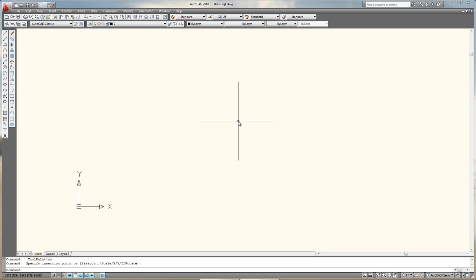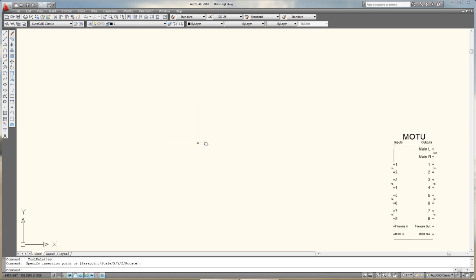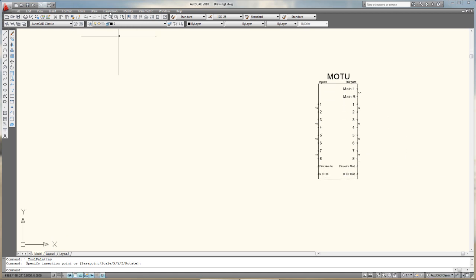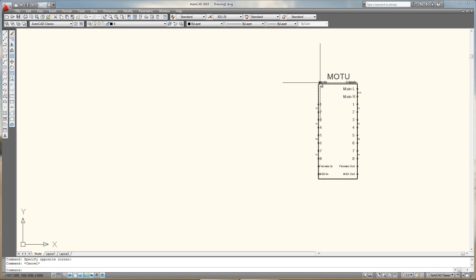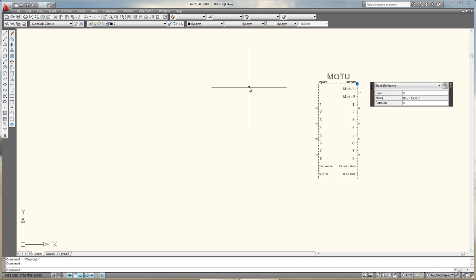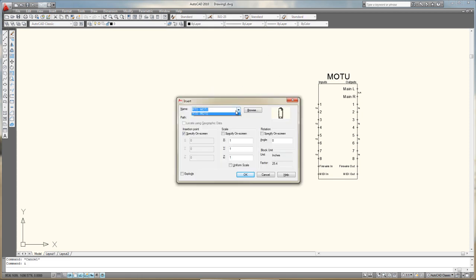And again, this is only if you use blocks in the first place. Like in my second year, I hadn't really found a full use for blocks, and this is an example. I just threw one in here in this new drawing one document, and this is an example of what I call one of my blocks, and that's the idea of what this is all about. A block by definition is just a series of created things that you've then said, I want to turn this into one clickable thing with one pick point. The idea being that if I want to insert it, I click I and enter, and then there it is.